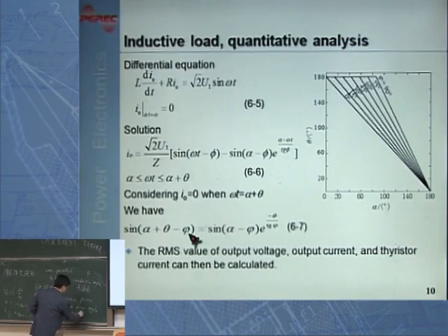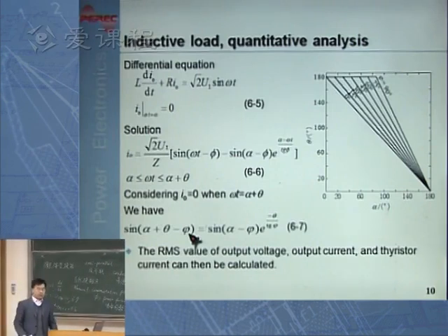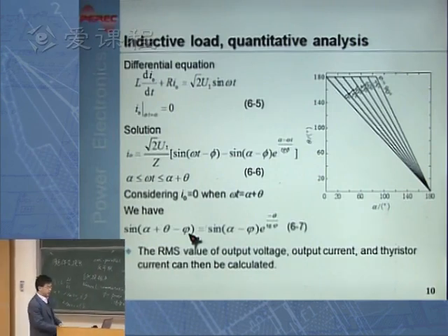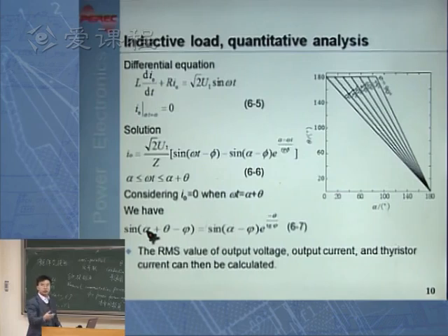So this conduction angle, finally, you can figure out, will be dependent on two things: triggering delay angle and the power factor angle.